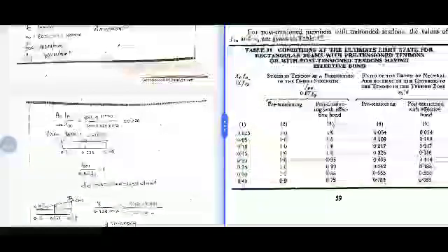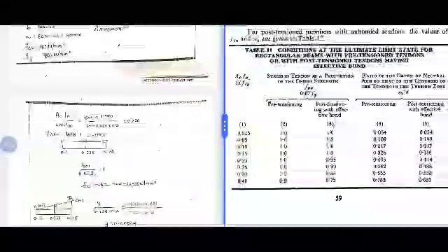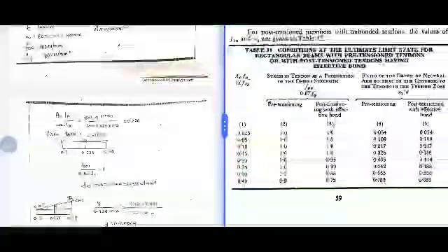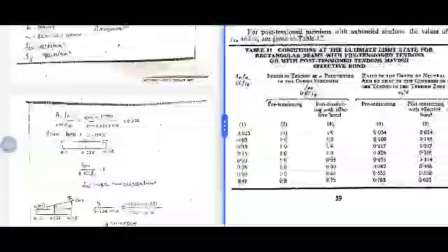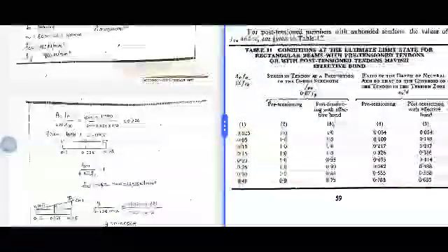Remember, in the question it is mentioned pre-tensioned, so you need to refer to the pre-tensioning case. For the effective reinforcement ratio 0.226, it lies between 0.2 and 0.25. For both we have 1 for the FPU by 0.87 FP ratio. So on simplifying, we will get the FPU value as 1653 Newton per mm square.